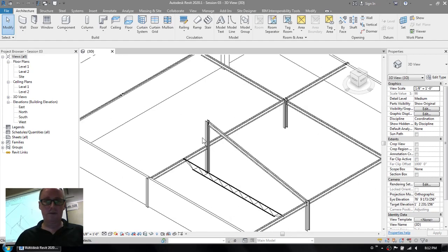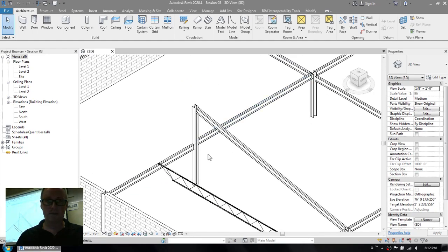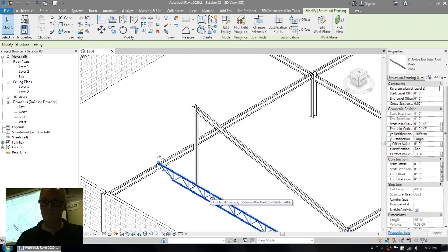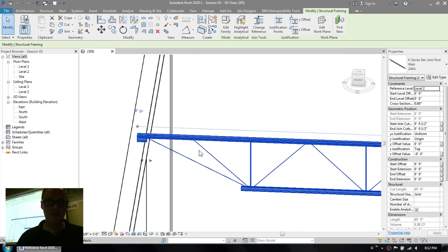We talked about the extension settings for beams, and the cutback settings at the end of beams, and the beam handle and the shape handle. So the round dot is your official sort of structural end of the beam, and then the triangular handles allow you to pull the non-structural end of the beam out.